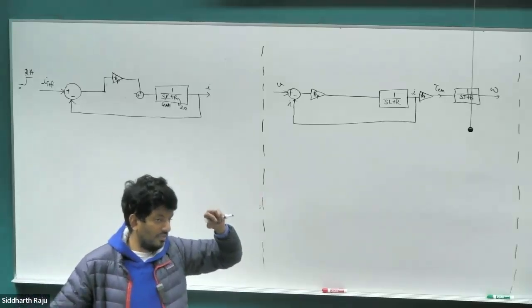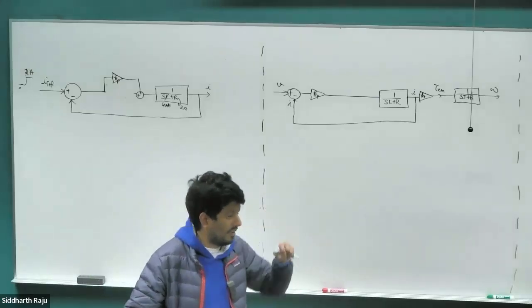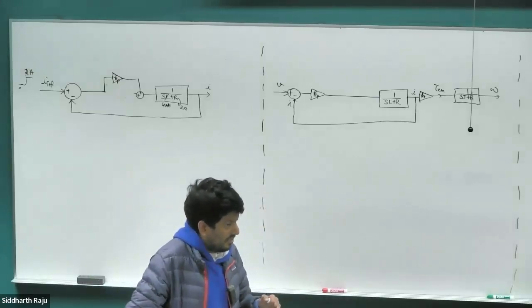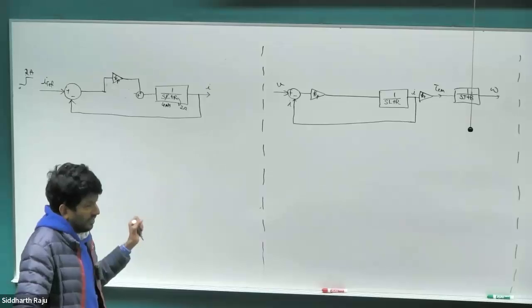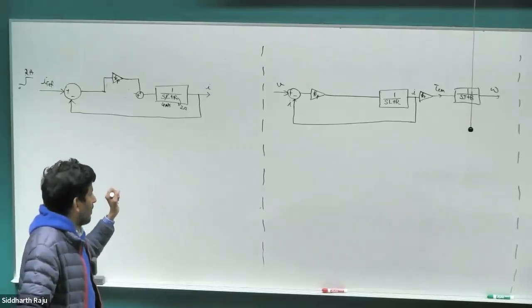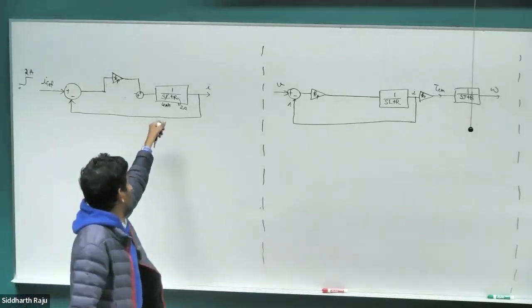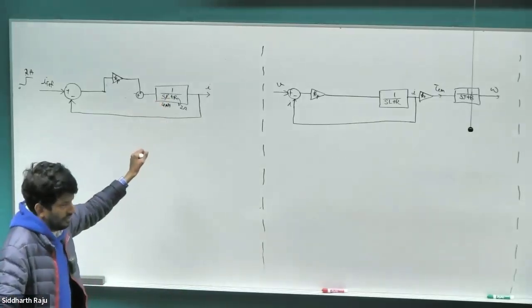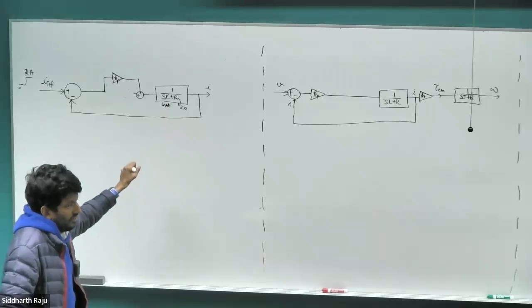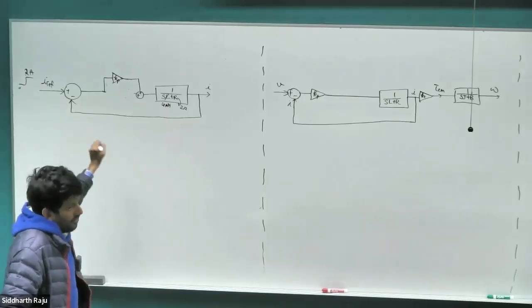Olivia, do you have an answer? Kristen, is the steady state 0? We can see when the error becomes 0. Is there a steady state? There will be a steady state, because as long as the motor has realistic parameters, like all positive R, L, B, and J, a DC motor always converges. If it converges, there is a steady state. Whether the steady state will match our reference is a different question.